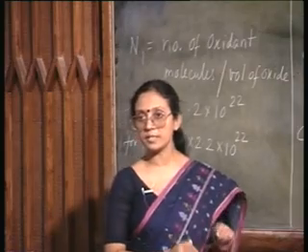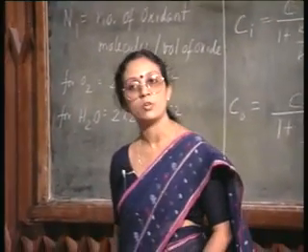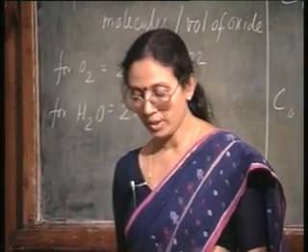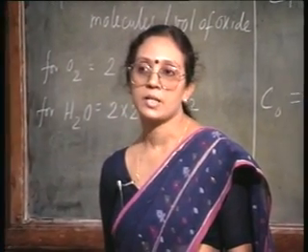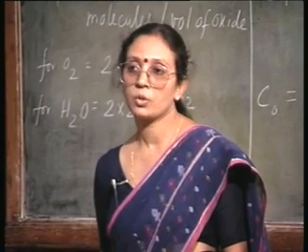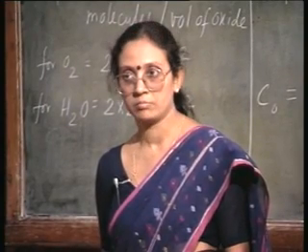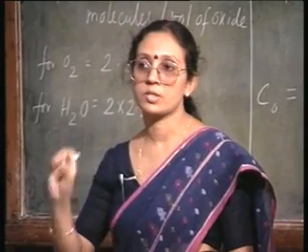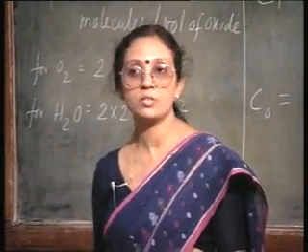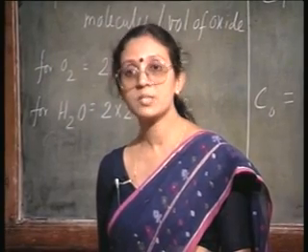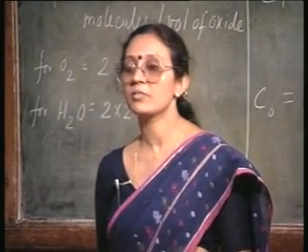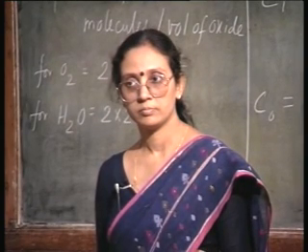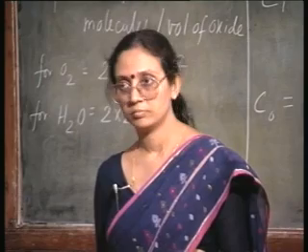Important numbers these, right. N1, that is the number of oxidant molecules per unit volume of oxide. Okay. So, you see, as the oxide is growing, the growth rate is given by dx dt. So, and N1 is the number of oxidant molecules incorporated per unit volume. So, N1 times dx dt is nothing but the flux of the oxidizing species. Isn't it?